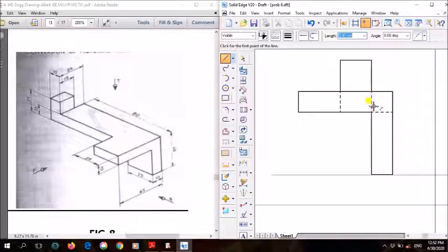That's why we have drawn these two lines using dotted line. And after that, whatever this solid is there, just forget this part and consider only this for this solid. There are two edges on that side. This edge is at the bottom side, so that edge is not visible from the right side, right? Hence I drew it using dotted line. Clear? So this is the right view.